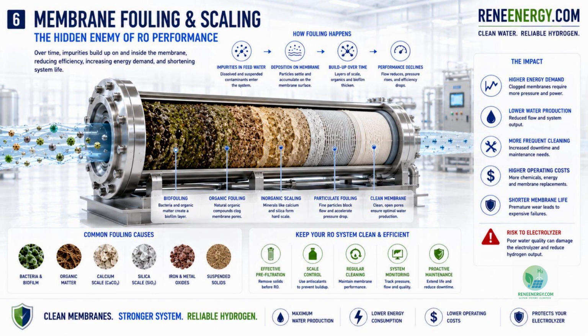Image 6 shows membrane fouling and scaling. This is one of the biggest hidden enemies of RO performance. Over time, impurities can build up on the membrane surface. Biofouling occurs when bacteria and organic matter form biological layers. Organic fouling occurs when natural organic compounds clog the membrane. Inorganic scaling happens when minerals like calcium carbonate or silica deposit on the surface. Particulate fouling occurs when fine particles block flow channels.